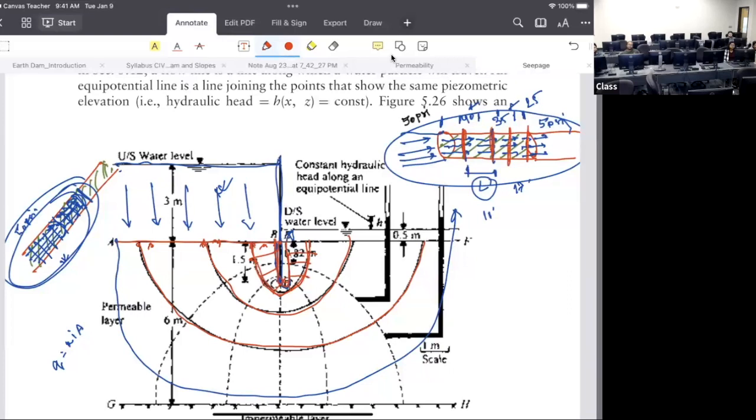So in this one, if we know the length of the pipe, here we need to calculate what? I, right? Yes. To calculate I, we need to know the head loss and we need to know the length, isn't it? That's it. If we know the head loss and we know the length, divided by each other, then we will get I.